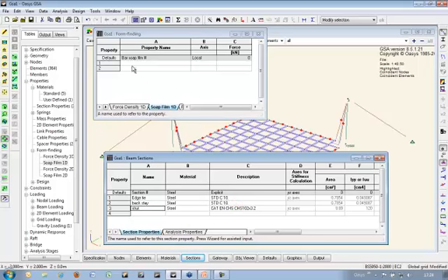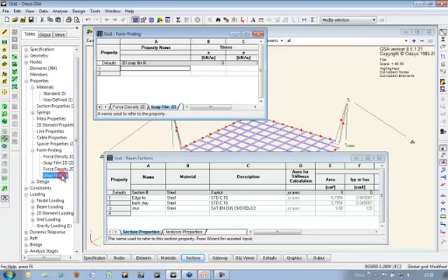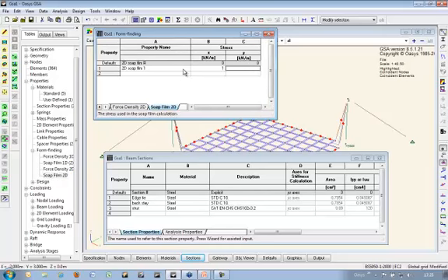Okay, so the 1D soap film properties, row 1 matches up with row 1 here. So this is edge tie, and I'm going to set a target pre-stress of 10 kilonewtons, and for the backstay I'm targeting 20 kilonewtons pre-stress. And so the form finder will try to find the geometry where these pre-stresses are achieved. In the soap film, for the time being, I'll just ask for a constant pre-stress in the two directions.